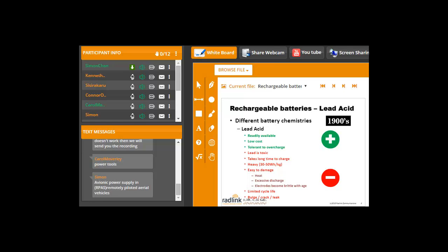But just for now, let's just say that if you were to purchase a 3.6 volt, 2400 milliamp hour lithium cobalt oxide cell, which you can buy from different electronic and hobby stores, you can charge that cell at up to 1C. What 1C means is you can charge it up to the same as its capacity, one times the capacity. So that's 2.4 amps. And you can charge it up to 4.2 volts, which is your maximum charge voltage.